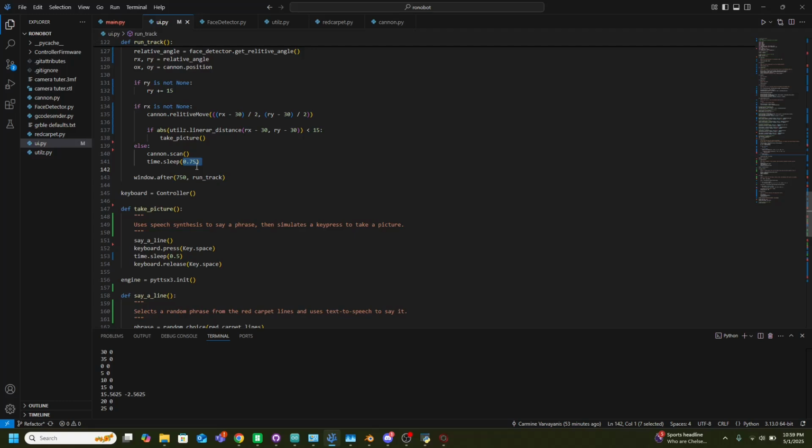moving again. Issue I ran into without that code was that the controller buffers the G-code commands, and they all kind of happen at once, and that was a bit of an issue, but this resolved that, right? Because what would happen is all my individual moves would get squished into a single move.